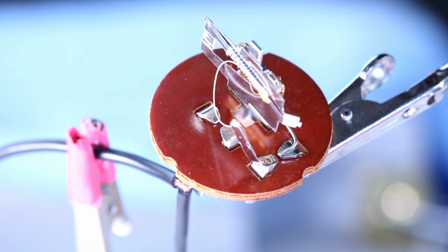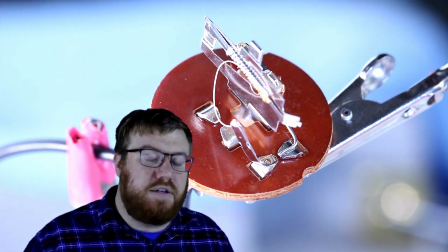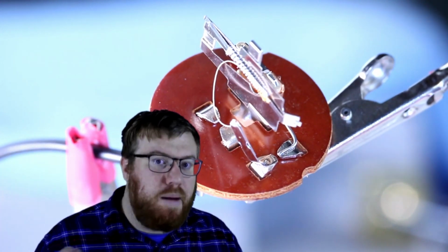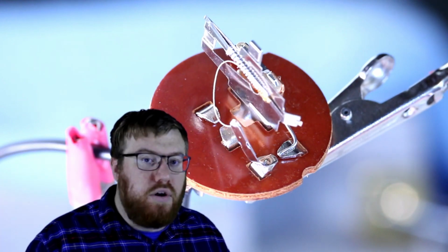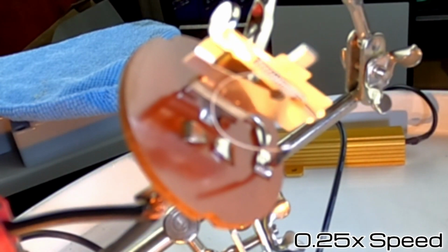Because electricity is now able to flow through an easier path, the first path can take a break and it starts to cool down. Eventually it cools down to the point where the metal will actually snap back out of place, and that secondary path for electricity is no longer available, and everything starts heading through that small wire again. This process will continue until the user turns off the turn signal. However, this will actually flash at different rates depending on how many bulbs you have and some other factors.